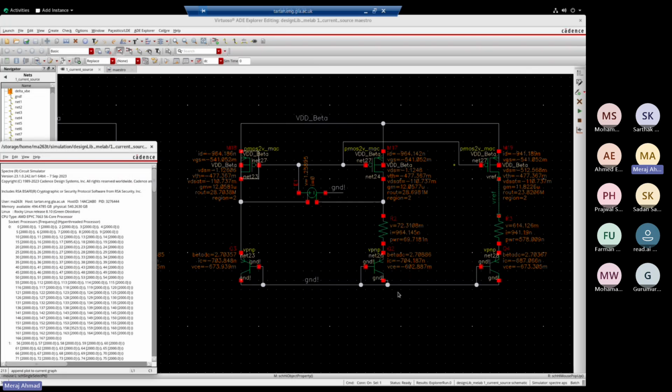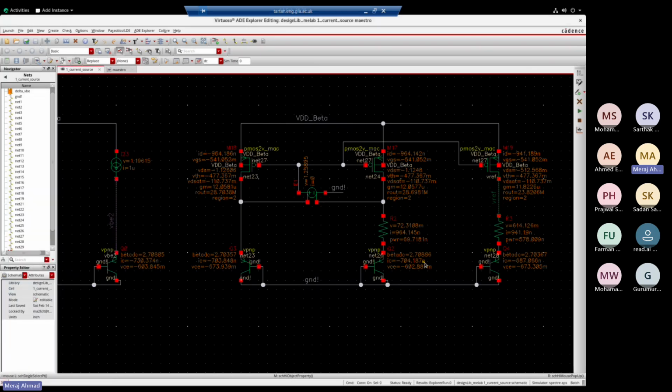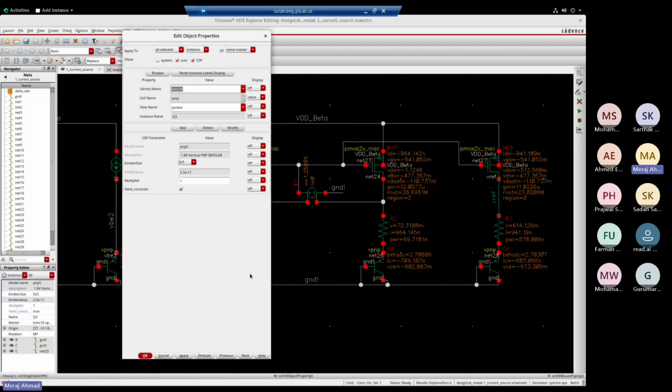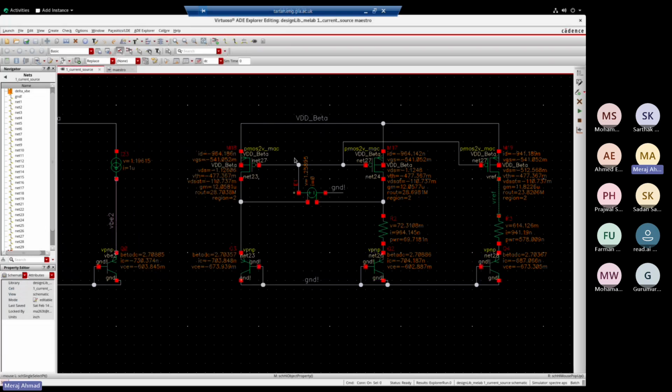In this whole design process, what are the variables? I took this from the technology file. There are only three sizes possible. To save area, I kept the lowest one. This is 15, and this is the same replica which is needed. So just arrange this and a resistor, and this current. Quickly you can have your bandgap ready with this.